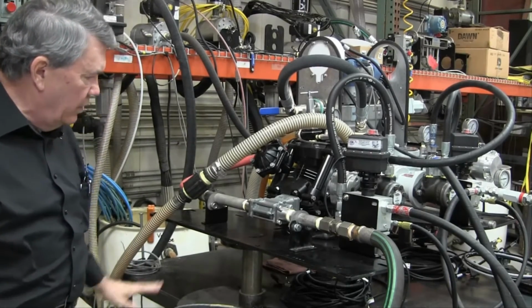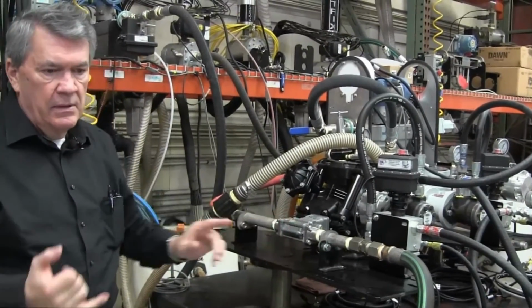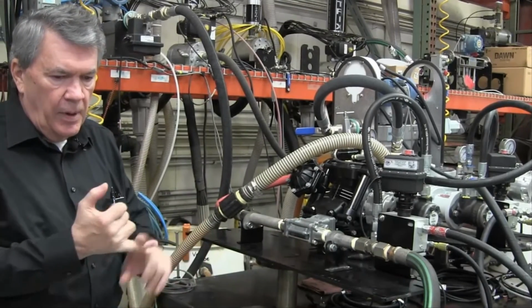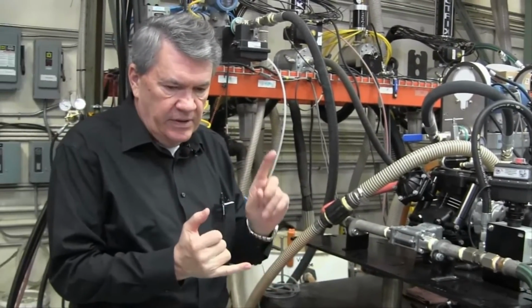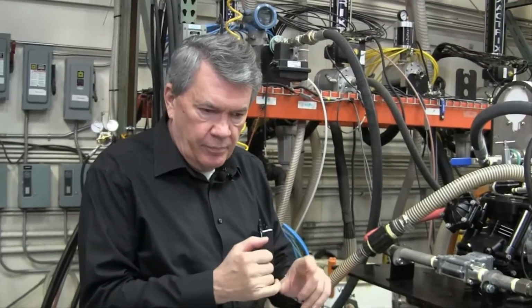Well, that's kind of the nomenclature discussion today. It takes 3 critical parts to make a good Exactrix system. It takes a PD pump that gets the pressure up and provides us tachometry. It takes a dual staging manifold, a high quality manifold, to get that 1% CV. It takes that terminal orifice to get the delivery right down to 1% coefficient of variation across the board. Thank you.